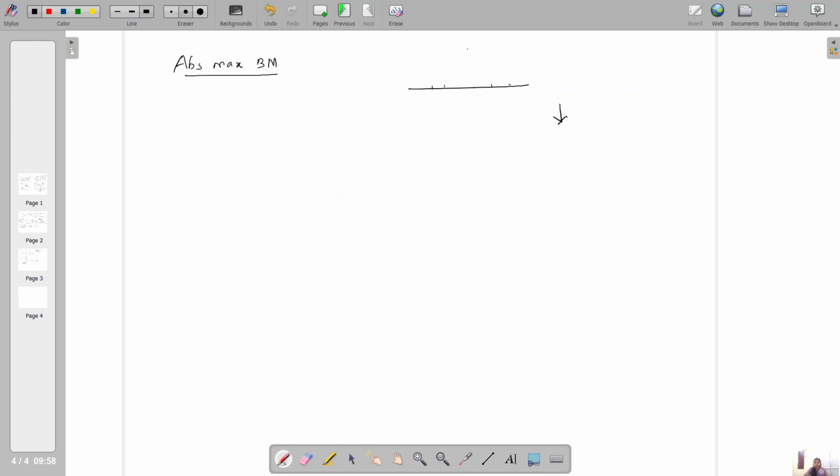Here we are having a point load. The center of gravity lies within itself, and the center of our beam is 30 meters, so 15 meter and 15 meter. Then this load is to be located over the center. The center of gravity of the load should be located over the center of the beam. So our load is 20 kilonewton.